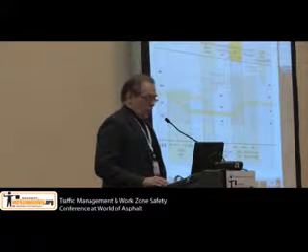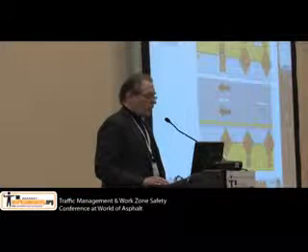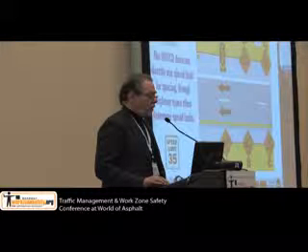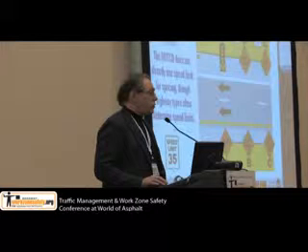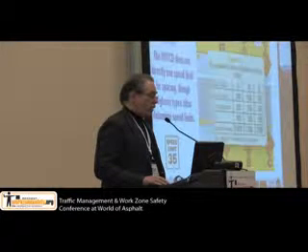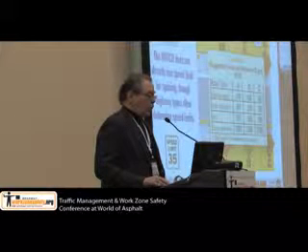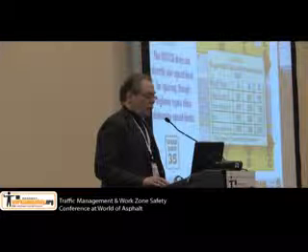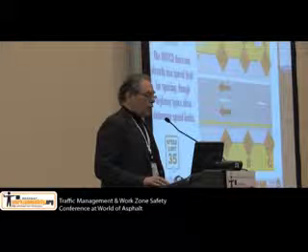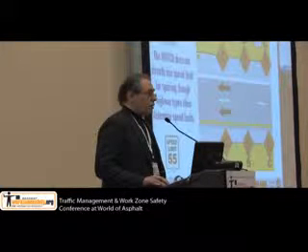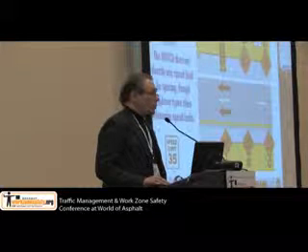Let's see, we've done the taper and we've done the advanced warning sign spacing. Spacing depends mainly on the highway type. The MUTCD does not directly use speed limit for spacing, though highway types often determine speed limits. Again, we can look at that table and see what it would look like here. We also have a little drop-down menu that will allow us to select the type of highway that we have. Like if we have a rural, and notice it will automatically tell us what that sign spacing would be based upon the criteria that we have entered.